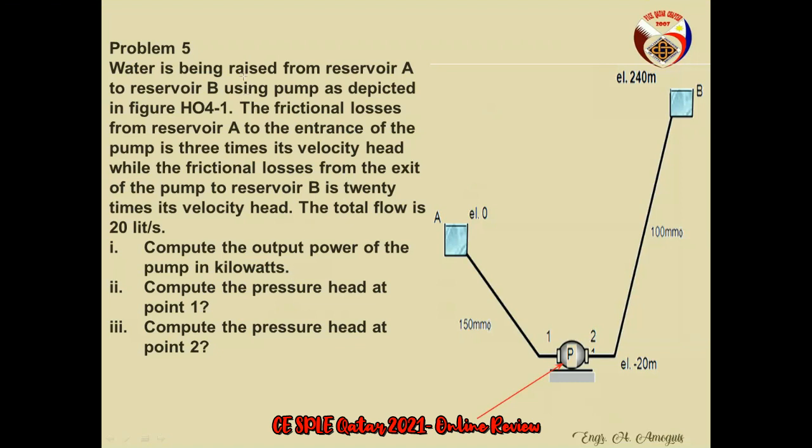So we know na yung power is a function of, di ba, the discharge. Ano ba yung formula ng power? Power is Q gamma times the head, no? So the head added by the pump. So meron tayong Q, that is 20 liters per second. Ang problema lang natin is yung head added.